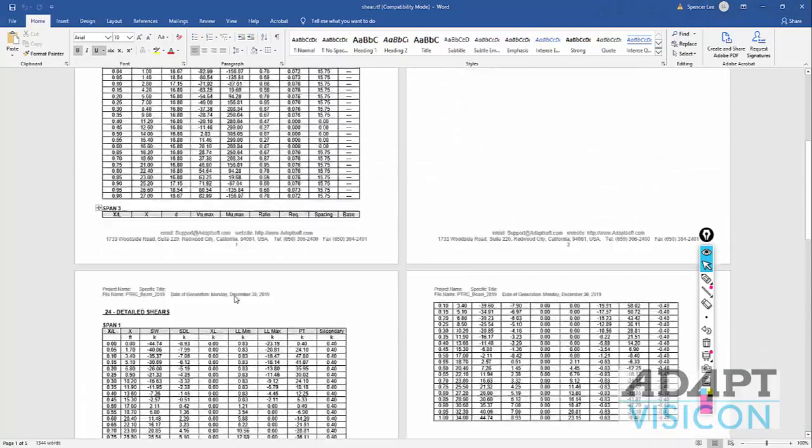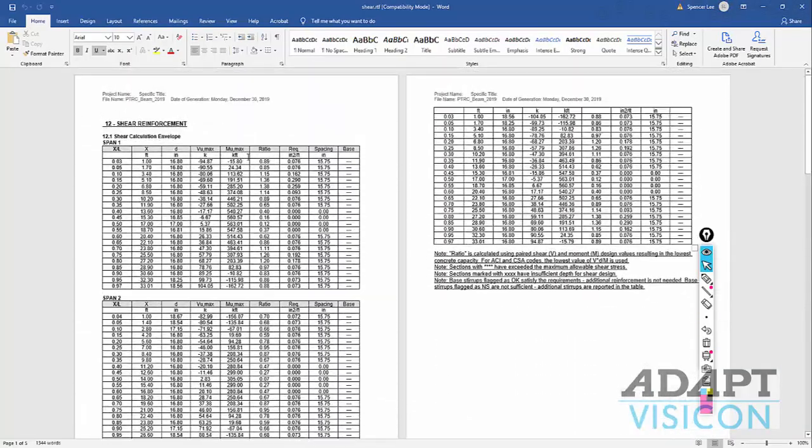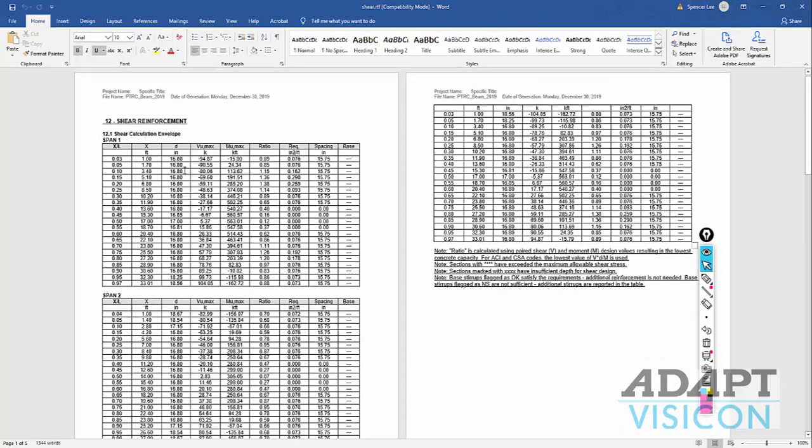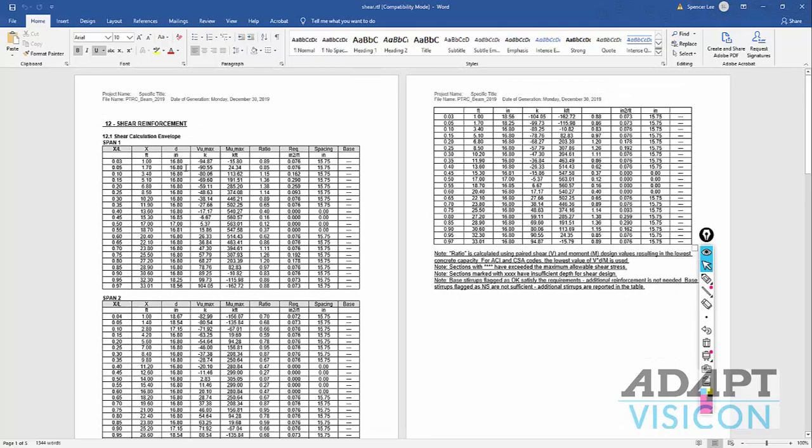The compact shear gives you the required area of steel and spacing based on the envelope of strength combinations. So this is not broken out into individual load cases. This is just the envelope at ultimate level for the shear. And again, any report that's available in the report generator can be produced in this tabular format in this way.